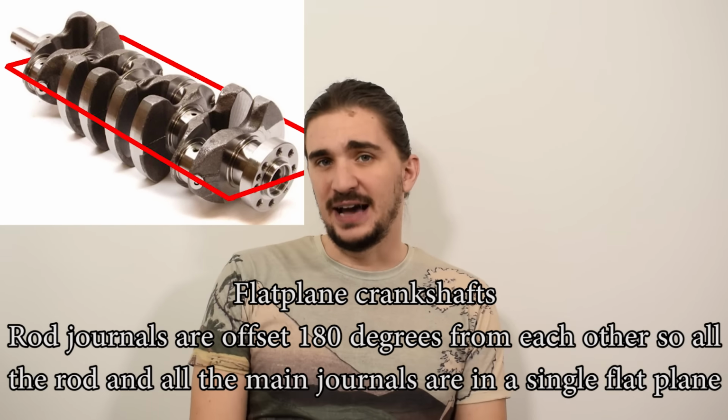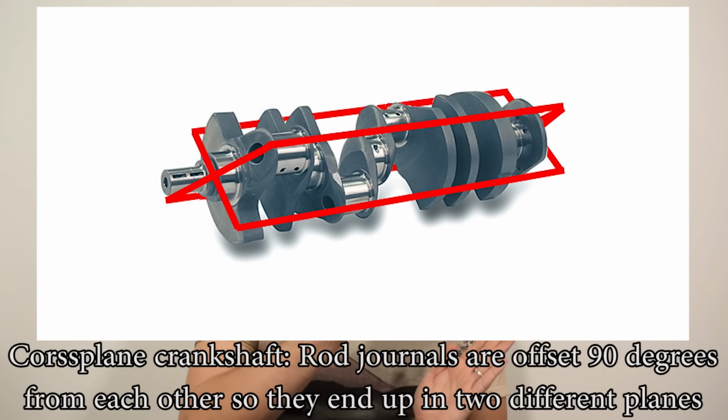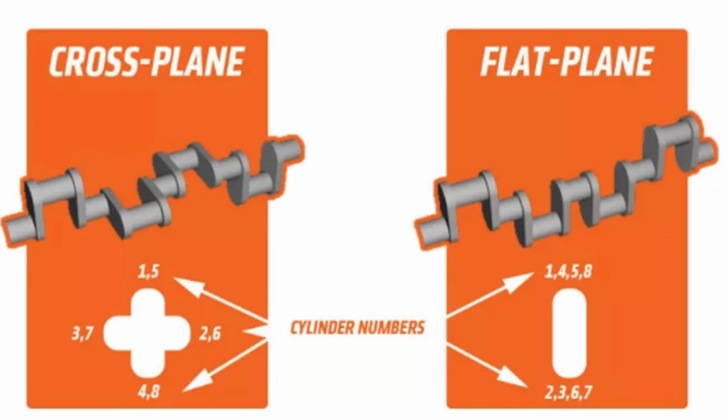Hence the name, flat-plane. On the other hand, a cross-plane crankshaft has the rod journals offset 90 degrees from each other, which results in the rod journals being in two different planes. And these planes are perpendicular to each other because the journals are offset 90 degrees, and hence the name cross-plane. The two planes are crossing each other.